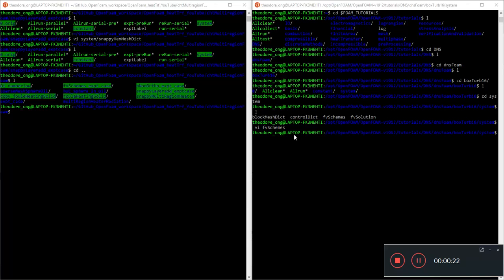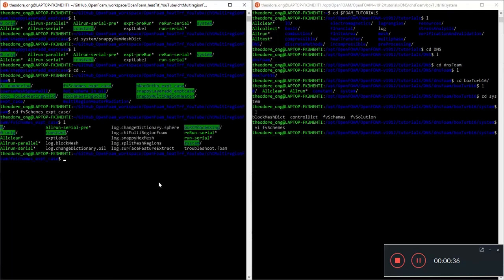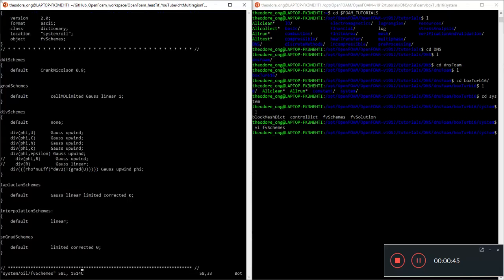So, in previous videos, we were talking about some of the experiments I've done that concluded that changing FV schemes would not help, because if you see changing FV schemes here, going to system, oil, fvSchemes, I've changed everything to Crank-Nicolson to try and stabilize the time schemes.